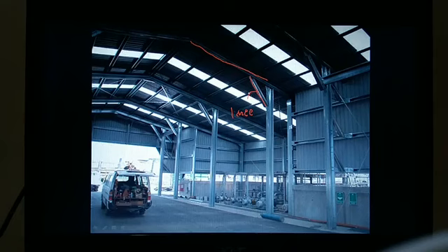What do you mean by knee bracing? It provides bracing between the column and the roof beam. So knee bracing will reduce the moment at the support. At this particular support, due to the eccentric moment from the load transferring with some eccentricity, this moment can be reduced by providing a knee bracing at the joint. That is the reason why knee bracings are provided in real applications, right?